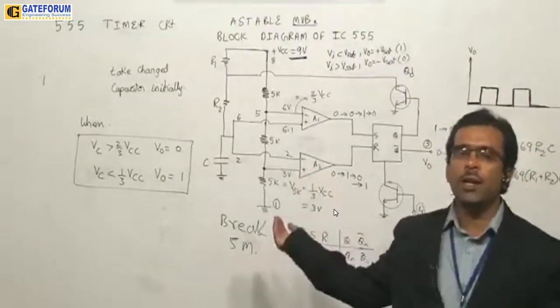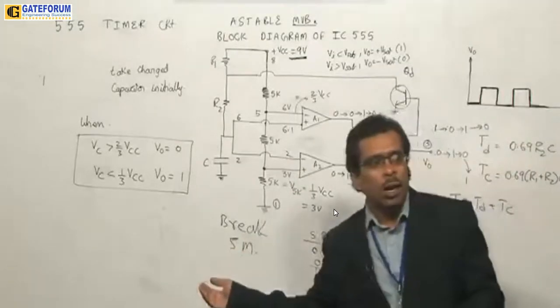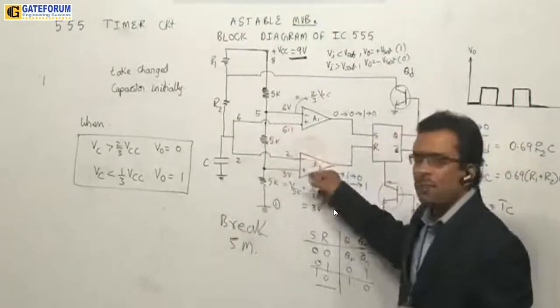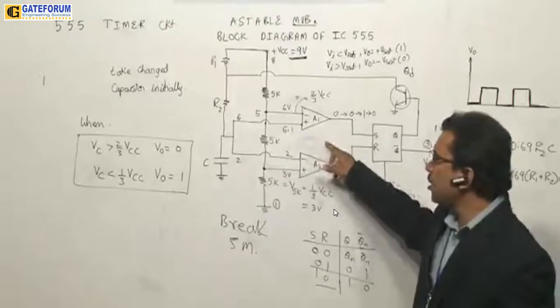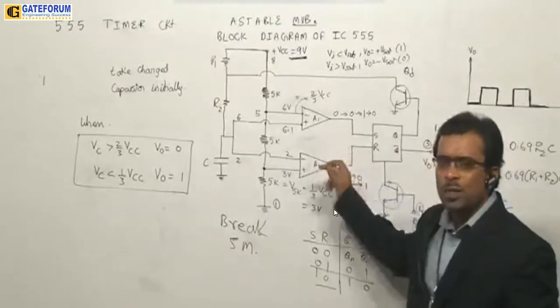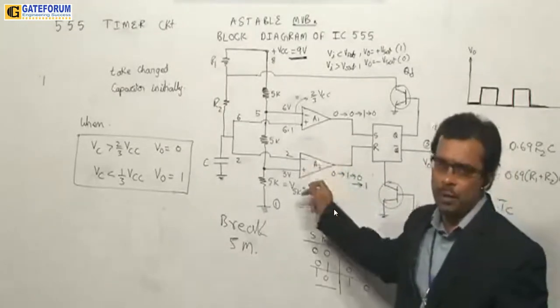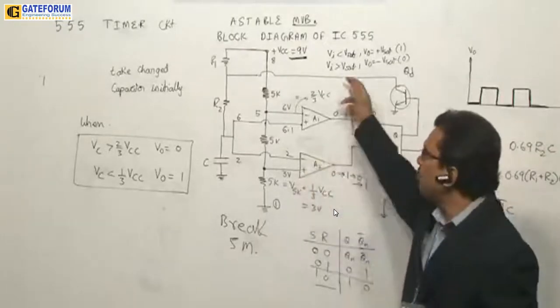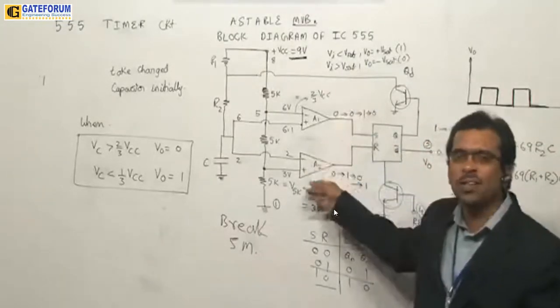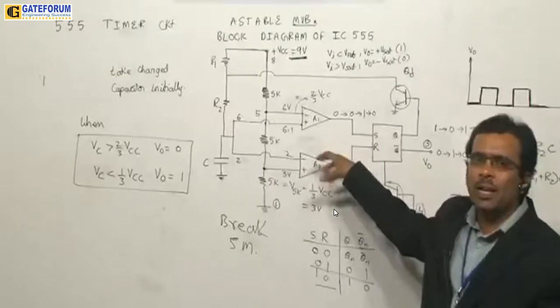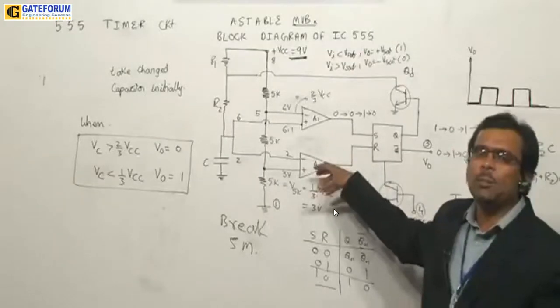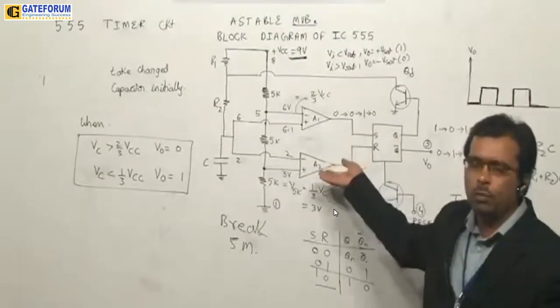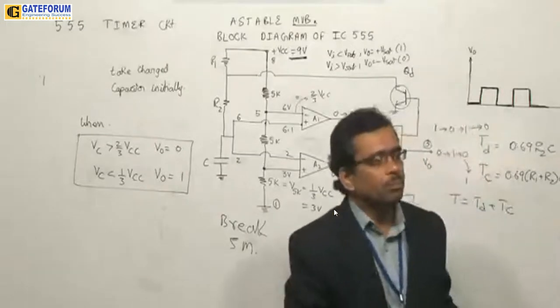This is specially designed for the application, because if you use a 741, the offset conditions will be more. But the op amp used here is not a 741. It is designed exclusively as a comparator. Anyhow, the comparator principle is always the same. That is the reason you will have fewer components, so less complexity. Because of that, more efficiency can be obtained from this circuit.